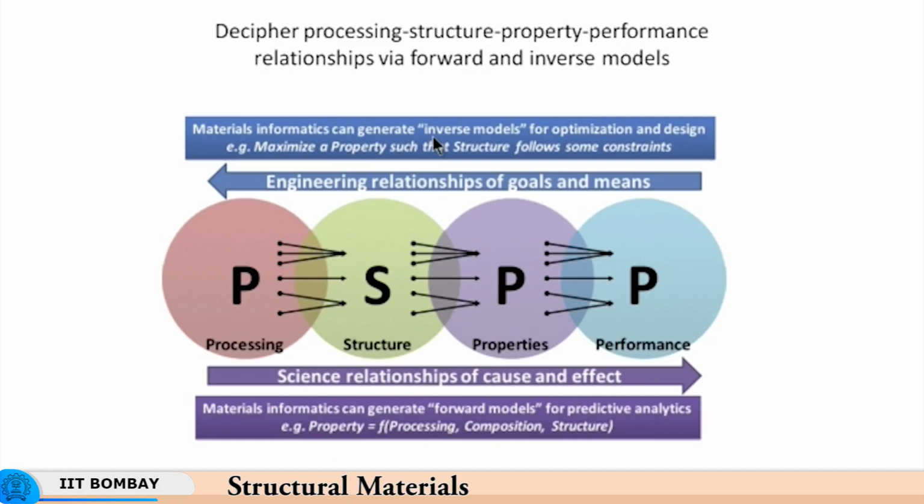So, in addition to chemical composition, I will have a parameter of cooling rate. So, I get an amorphous structure which will give me certain properties, and by virtue of the amorphous structure I can get a very high amount of ductility under superplastic conditions because of the very fine grain size or amorphous state, and thereby I can get a certain degree of performance from the product I make using that particular material.